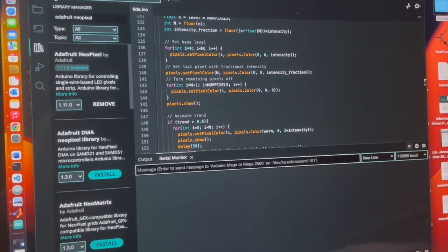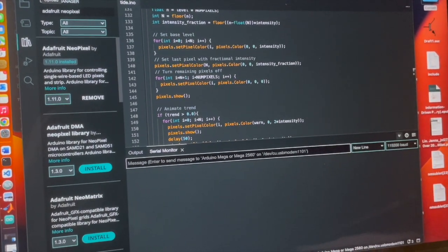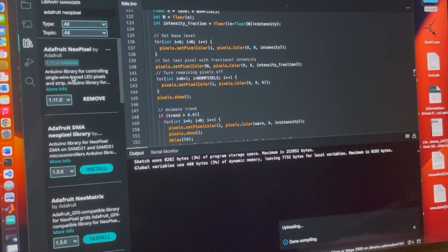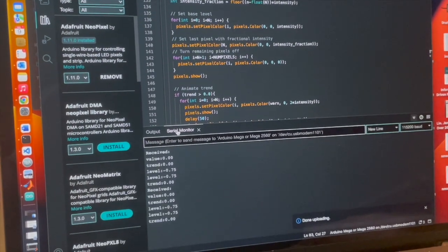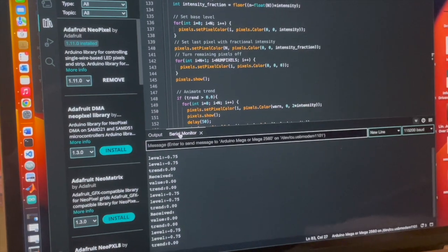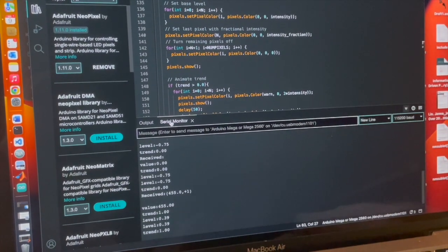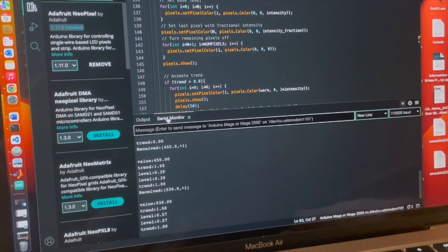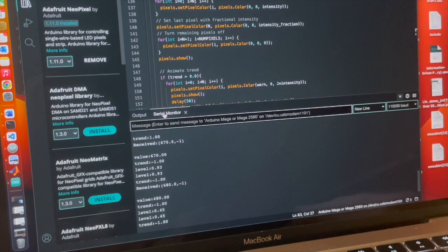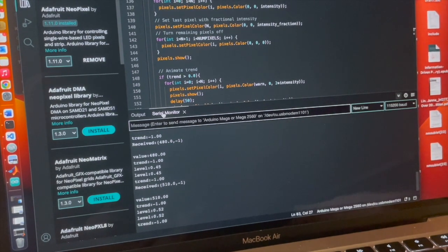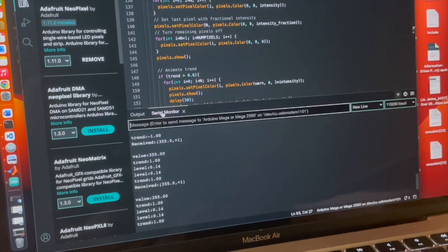In this code, we have the Arduino code, and we're now uploading the code onto the Arduino Mega board. Now, by looking at the serial monitor, we'll be able to see something is written out, but it hasn't received anything yet. Now we have seen "received," and then there are some numbers after that. This means we have successfully received the data we're supposed to send. And that means our UART communication is working successfully.